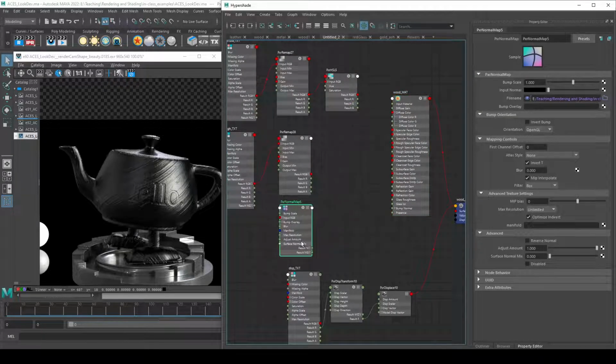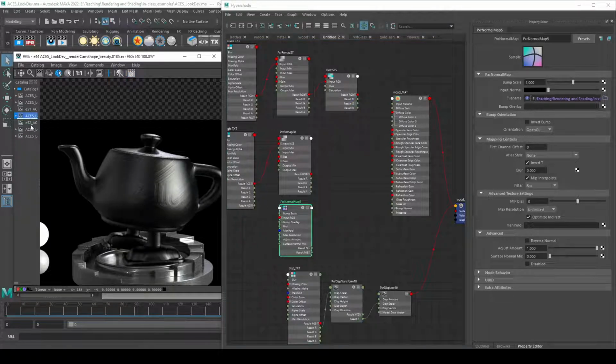But usually what people do for VFX is, if the surface detail changes, like these little bumps and ridges, are small, then the bump map is totally great. It's cheaper, it's light, it's efficient, it's easy to use. It's fake, but you can't tell. But any big surface changes, like maybe these letters, require a displacement map. Anything that's a really big surface change that we're going to notice is kind of faked by the normal map, we might want to use a displacement map for.